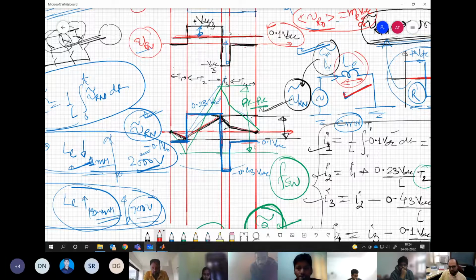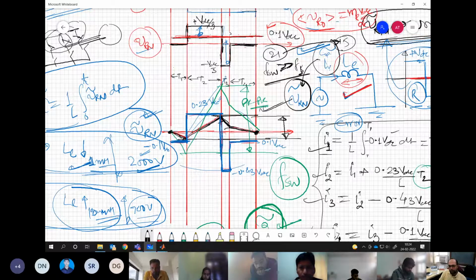The only thing we need to keep in mind is that when we start from 0, we must end up at 0. And this assumption is true as long as your switching frequency, say, is larger than your fundamental frequency, and the boundary can be 21. Sometimes this may be true for 15 as well, but as you start going below 21, you may start seeing some slight difference.